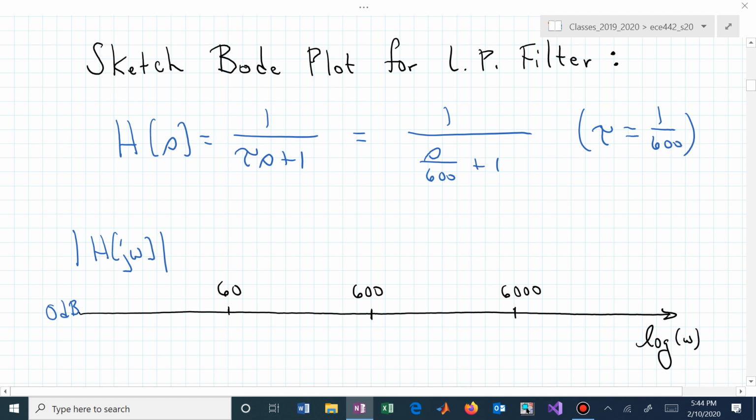It's kind of confusing a little bit, but it's really tau s plus 1. That's time constant form. We've normalized the constant to 1. We've made the tau explicit, but in fact, we've written tau as 1 over the pole. And so we can actually see the pole at 600 in this time constant form.